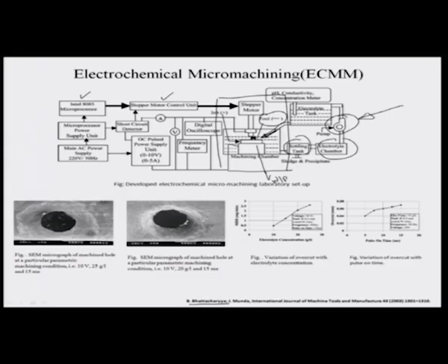There is a stepper controlled motor which gives drive to the tool, okay, and this ensures the quick start and stoppage of the lead screw drive which would actually feed the tool towards the workpiece.